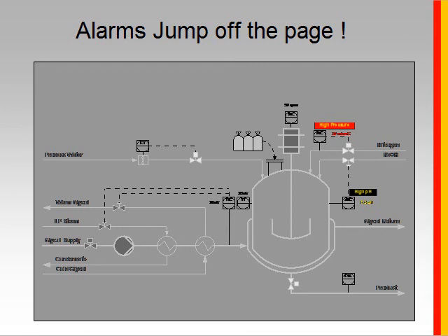So the idea of making it so the operator quickly and easily sees the presence of the alarm is followed in this design. If we think about the differences between the two, we see that the colors yellow and red are being used to indicate the presence of an alarm. The standard does not dictate what colors must be used, because that really differs based on system and culture and region of the world.